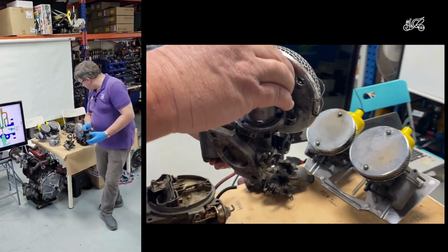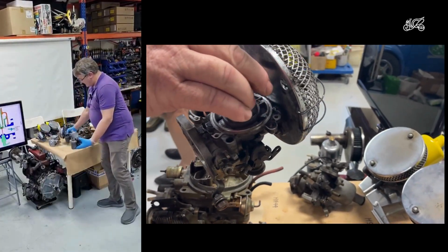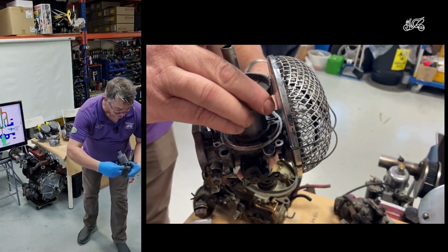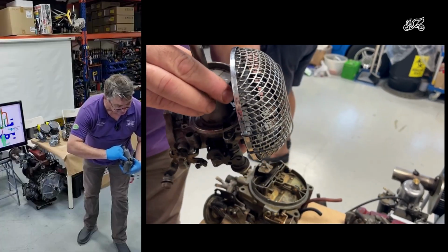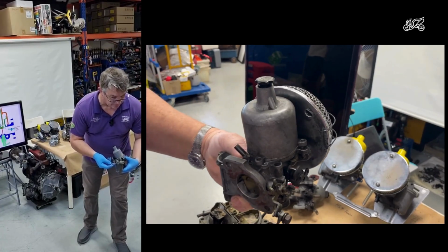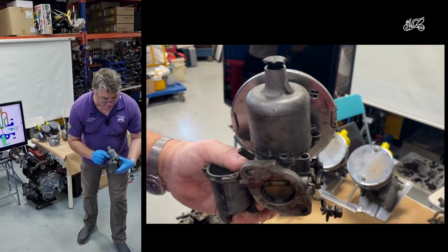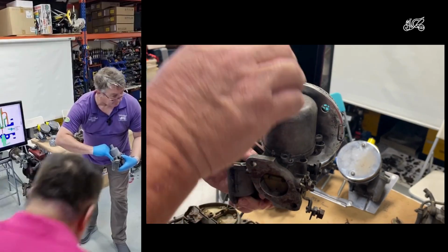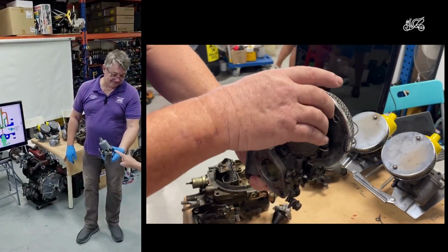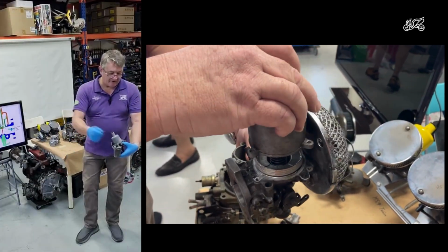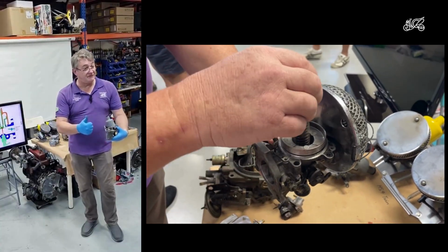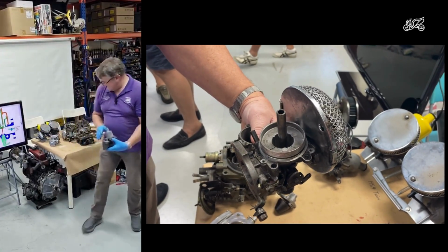Right, so there's one with the top on, and it's got a little hole down there. So the fuel goes in there, beneath there's a little bleed hole, and if the float or the needle sticks, you start to see fuel coming out of that hole, and it floods down there. So just knock this area. Give that a knock, and if the thing dries out, you fixed it.